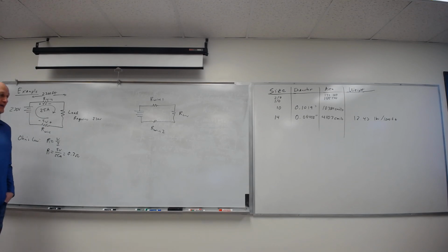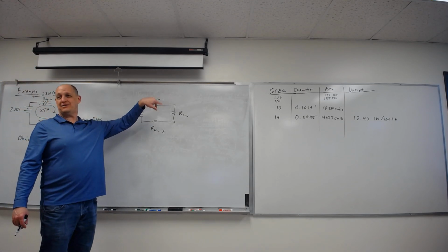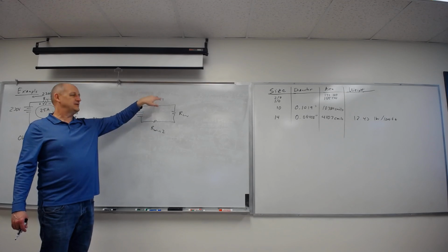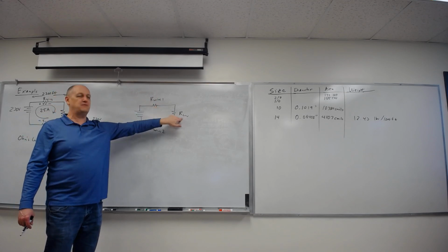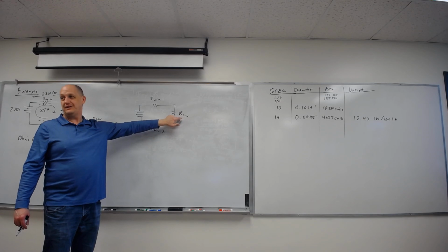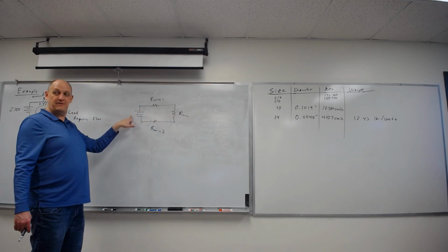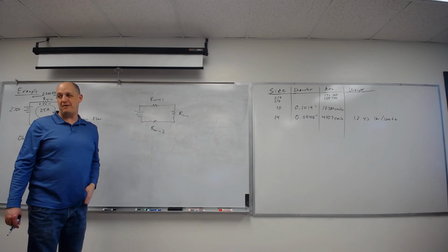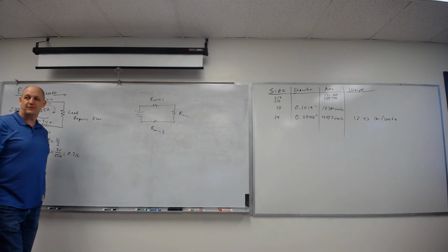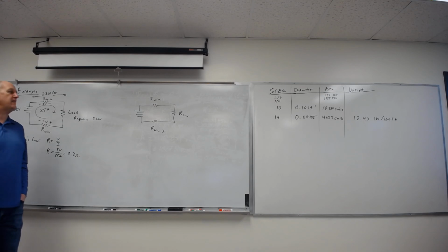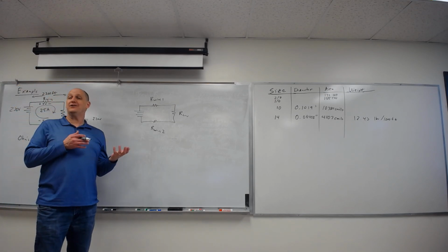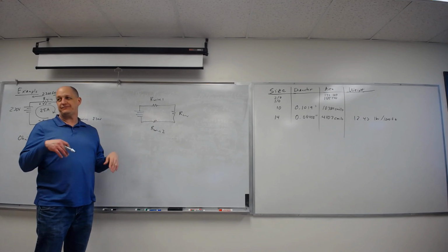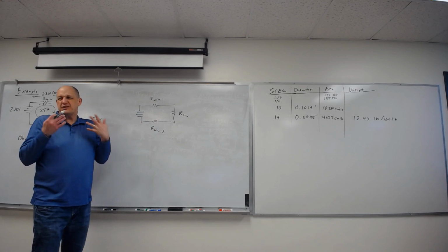To solve this, all I have to do is go, oh, this is just a series circuit. My resistors in series, and I can find my total current, use my current to find the power being dropped across the load. And I can find the power being generated by the battery and figure out how much power I'm losing in the wire as I transmit my current from one end to the other of this long wire. Then I go back and say, if it's an ideal case and these don't lose anything, how much power would I transfer? So just do those calculations.